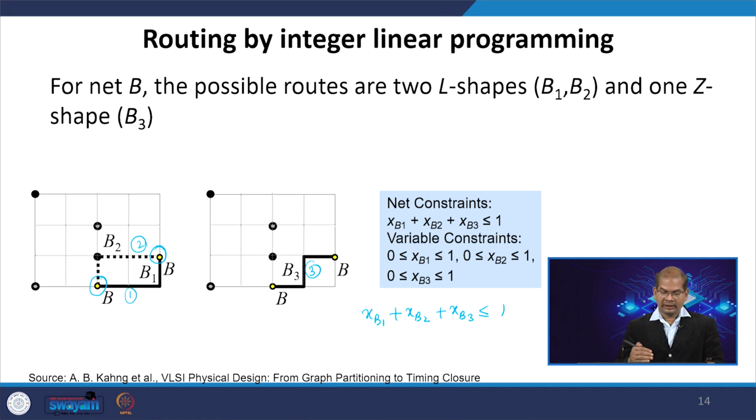So, we are analyzing each net independently, we are not looking into the other nets at that time. But when the ILP solver is used, it will check that if I go by this route, whether there is a short with the other net or not. That is the job of the ILP solver. It will check if there is any kind of violation.